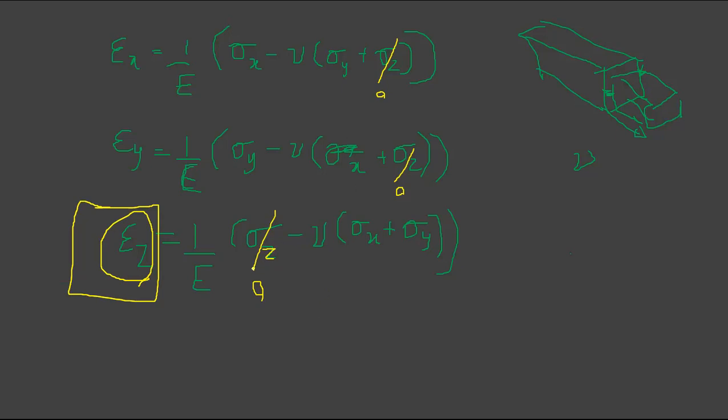So your stress in any one of the three axes is simply 0, right? So you are working under a 2D state of stress actually, but your strain is there, right? Strain is essentially in all three normal directions, right? So this will give you normal strain, right? So this gives how epsilon is related to the stress. So we can simplify and write some equation for the stress as well.